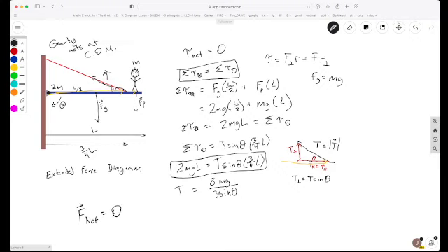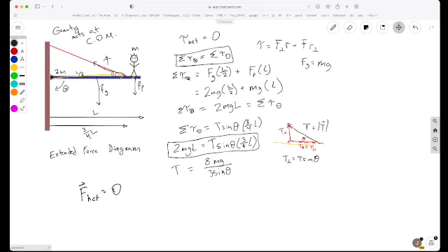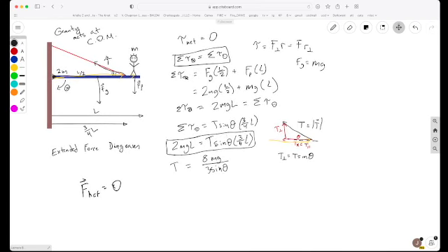Right, so the torques that all the forces make have to add up to 0. But these individual forces also have to add to 0, because this whole thing isn't moving, right? This plank is stationary. So let's do what we're used to with balancing x and y components, except now there's maybe one more force we have to take into account.